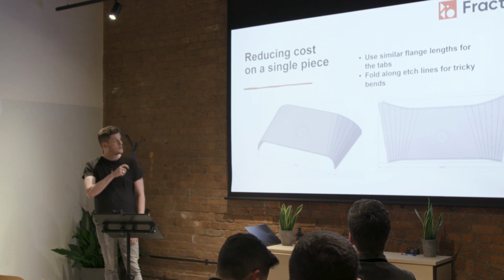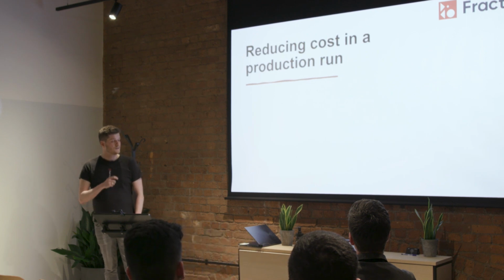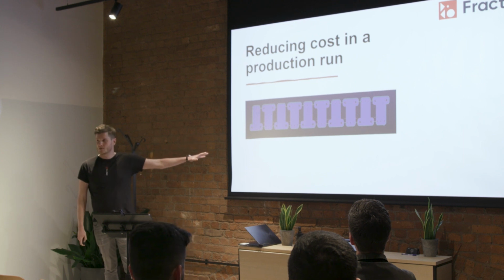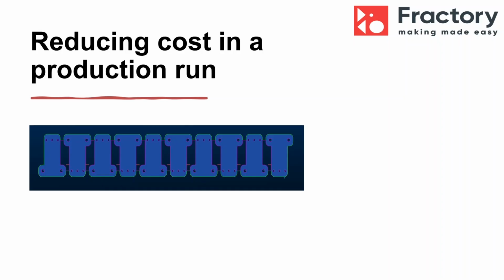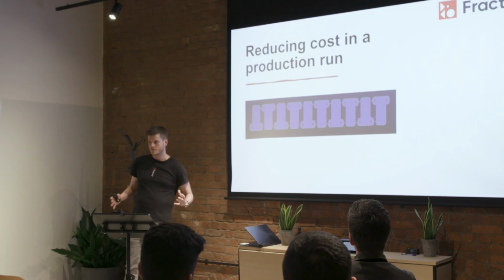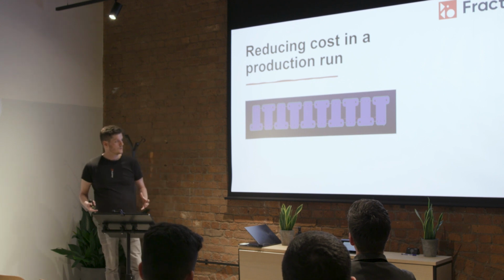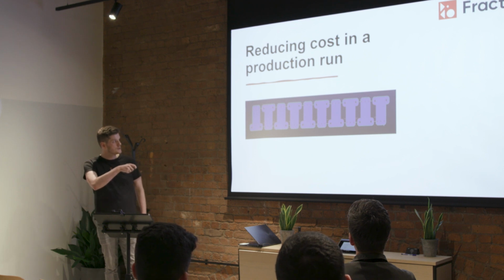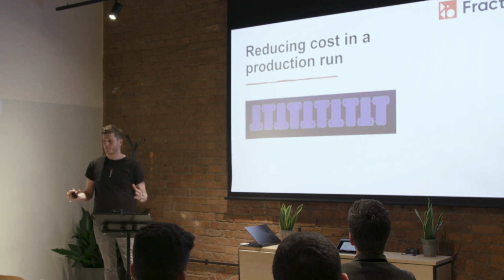The next design we have is for small brackets, which have been made in the tens of thousands. Now, these brackets were originally all just one piece each. Each one has 2 folds on either end and 3 tap tolerances. We needed to be able to get these produced at very quick speeds for the clients, and what was proposed was actually tagging these all into each other to turn these 10 brackets into just one piece that comes off the laser.